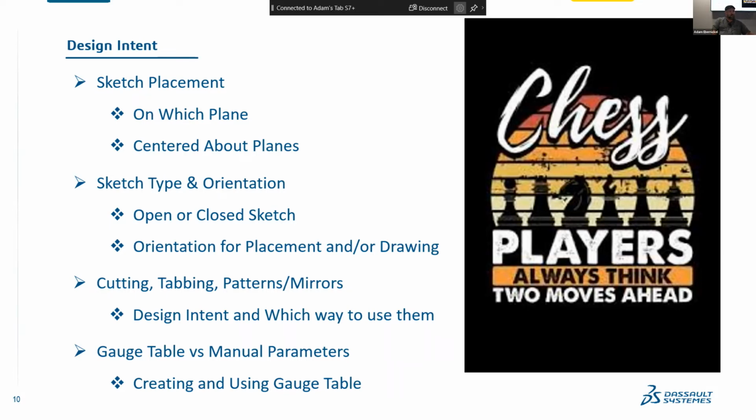A good point we brought up earlier in today's meeting this afternoon was, where should the fillets be? If you're going to fillet the edges of your sheet metal or any extruded part for that matter, where should it be? Should you do that first, up in the higher part of the hierarchy of your feature tree? Probably not. It should probably be at the bottom. It should be one of the last things you do, because if you have to simplify the part, it's an easy thing you can delete without ruining or wrecking the rest of your model, right? Plus, SolidWorks is going to solve it a lot easier that way too.